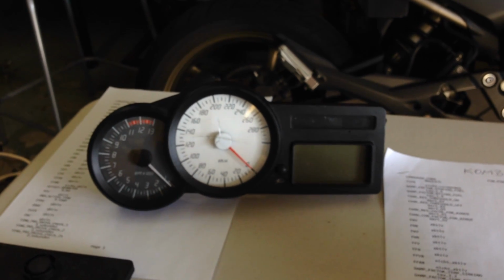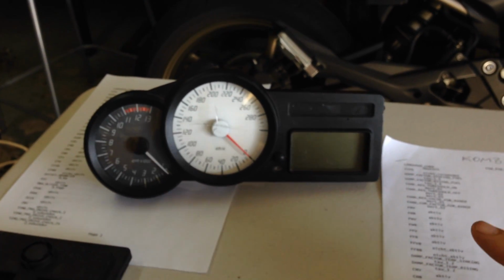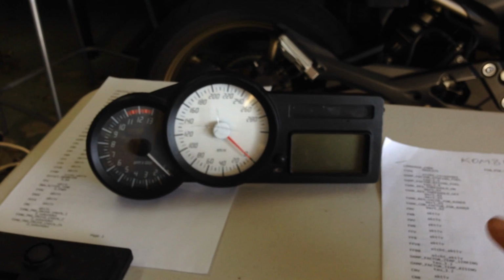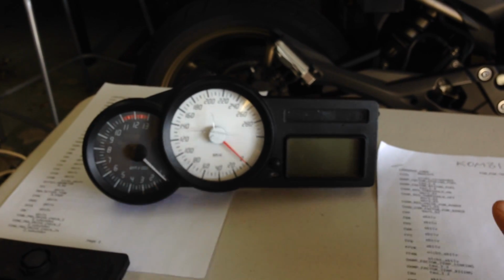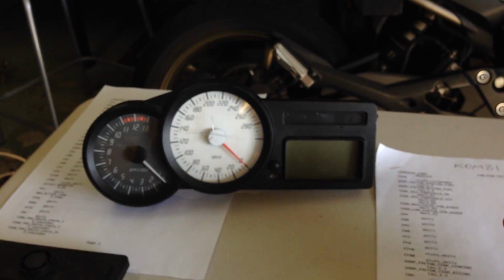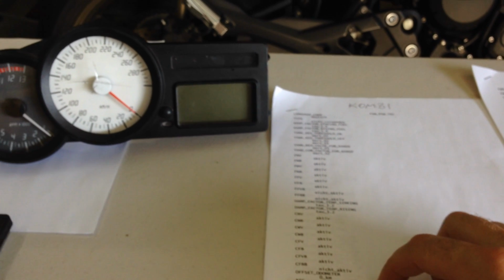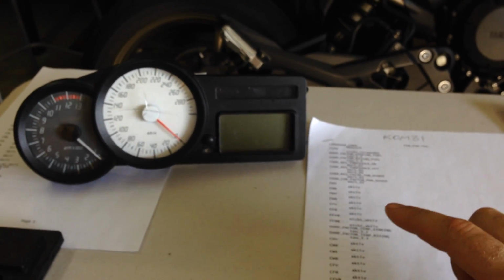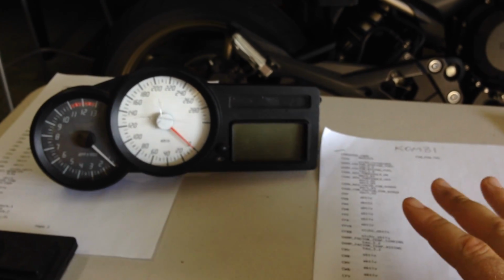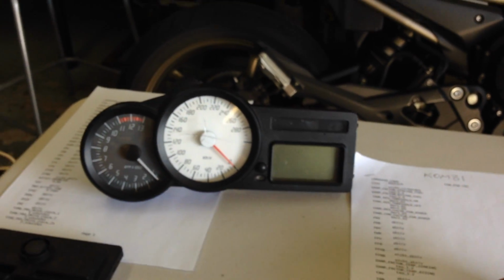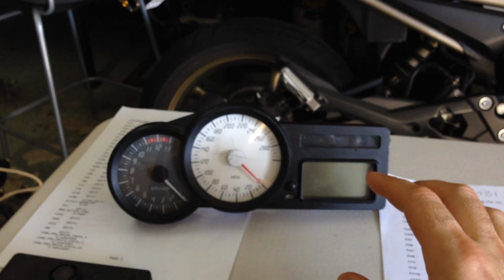When I hooked this up and turned the key on, the motors of my ABS unit, the pump motors, instantly came on and wouldn't turn off. So I had to change a few settings to tell the instrument cluster what sort of ABS module I have, and then recoded it, and then it turned off. So I got this to work.